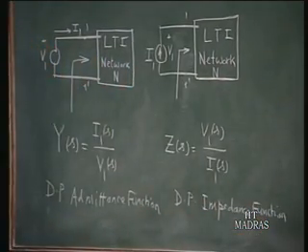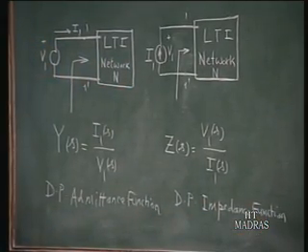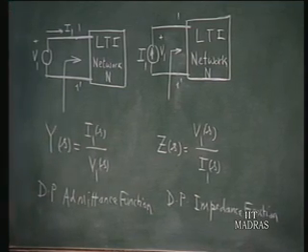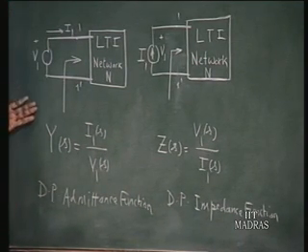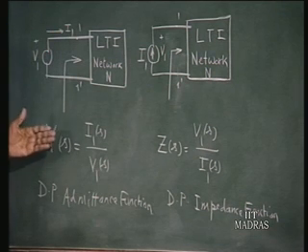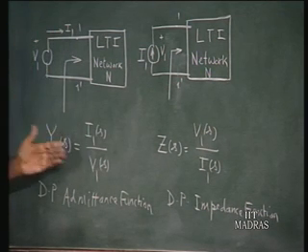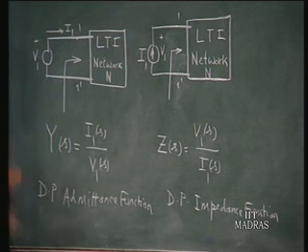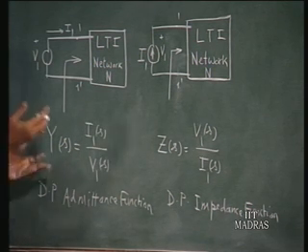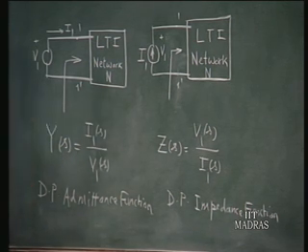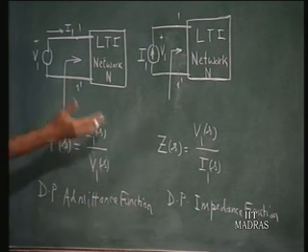The idea in defining these functions is that if we know y of S, you can calculate the response for any voltage input. You know the current, because after all I1 equals y times V1 of S. So for any other excitations you can immediately find out the current. Similarly, if you know the current excitation, you know the voltage for the corresponding current excitation knowing Z of S.